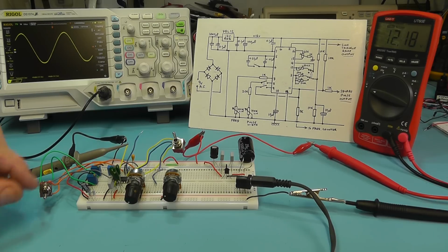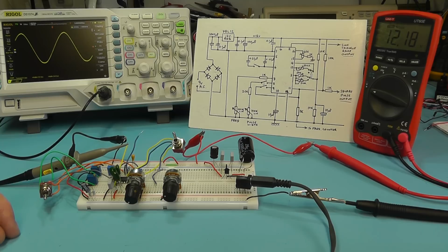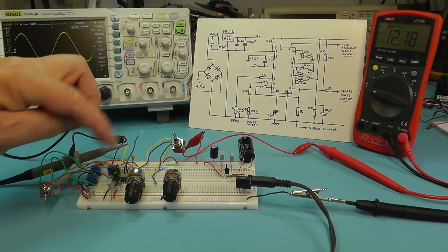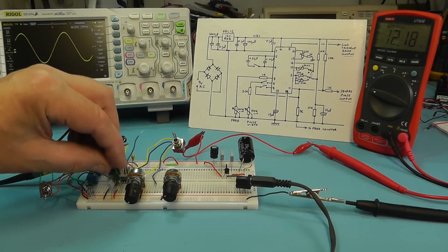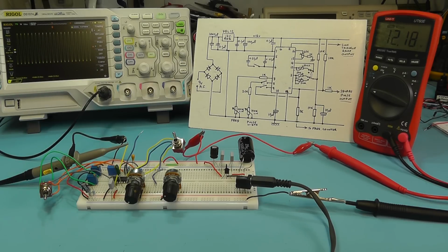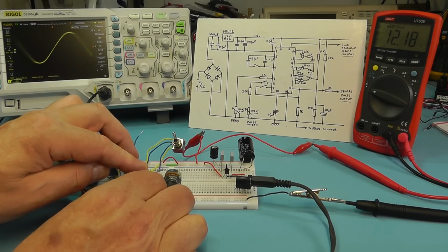Now what I'll do is I'm going to remove the larger of the two timing capacitors and just monitor the output waveform frequency. And normally we'd have a switch in here, but just for the purpose of the breadboard I'm just going to remove it. Well, immediately you see the frequency shot up there. It's now reading just over 17 kilohertz, but let's just see what the minimum frequency is this time.